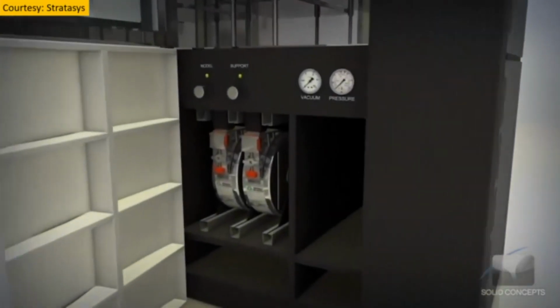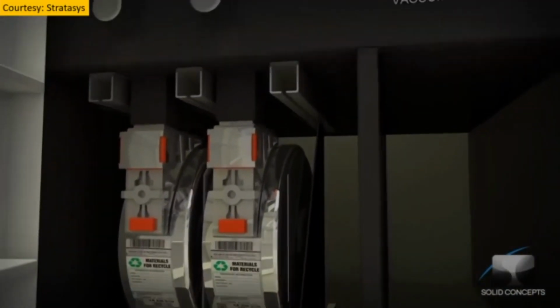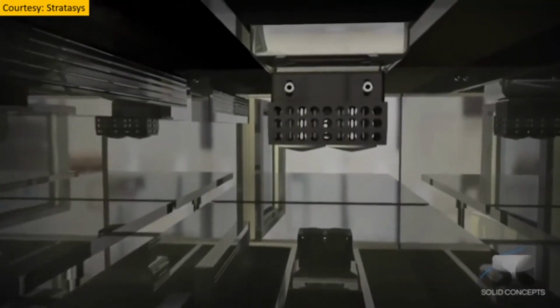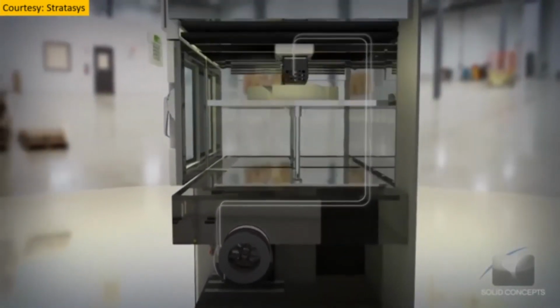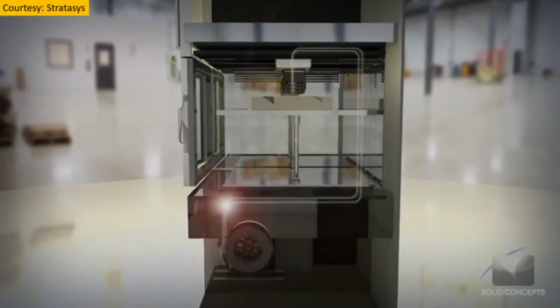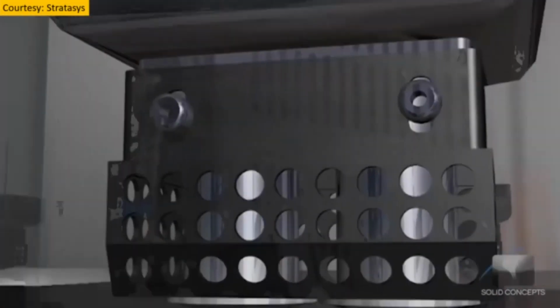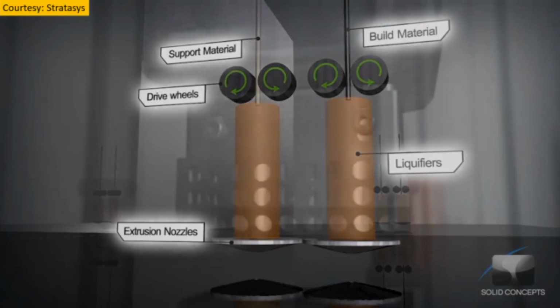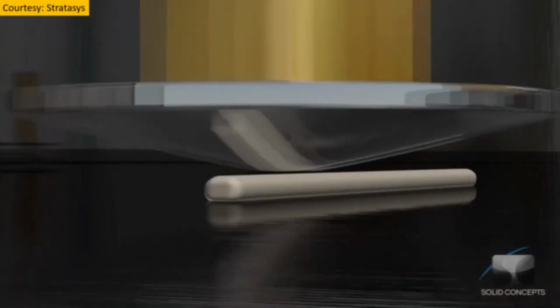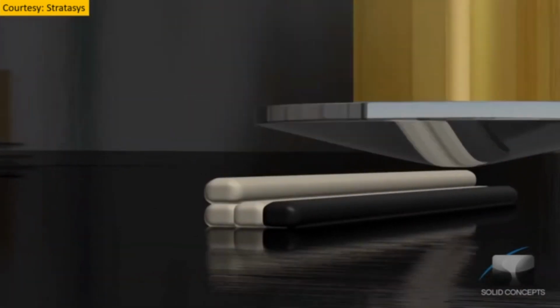This video by Solid Concepts can explain the process further. There are two reels on the bottom side, and you can see they supply the main material and the support material to the liquefiers. The main material here is in black color, and the support material is in white color. The wire gets transferred to the liquefiers, where it is heated and melted. The solid portion of the wire acts as a piston and pushes the molten material through the tiny orifice.